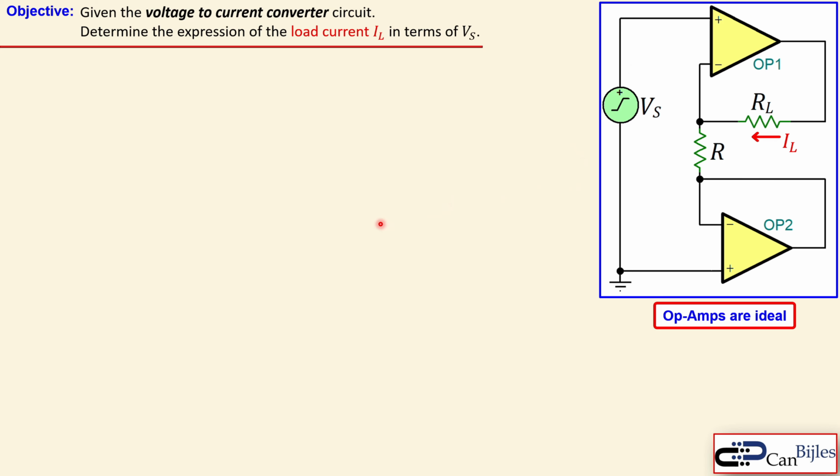So how do we do that? First the calculations, of course, and then we will see what we have done and verify this in SPICE simulations. Before we move on, let's use the op-amp ideal characteristics. In an ideal op-amp you have no current inside, so this current is 0. The current here is also 0 in the non-inverting input, and also in this non-inverting input.